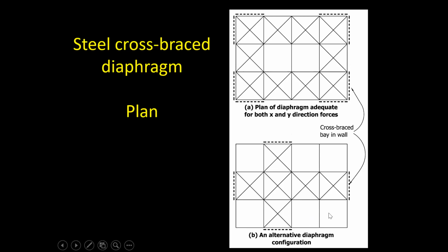And so you've got to show this bracing in your roof structure that is creating this diaphragm as horizontal structure. And every wide span structure needs diaphragms like this to tie your roof together and to transfer your forces sideways into your vertical bracing.